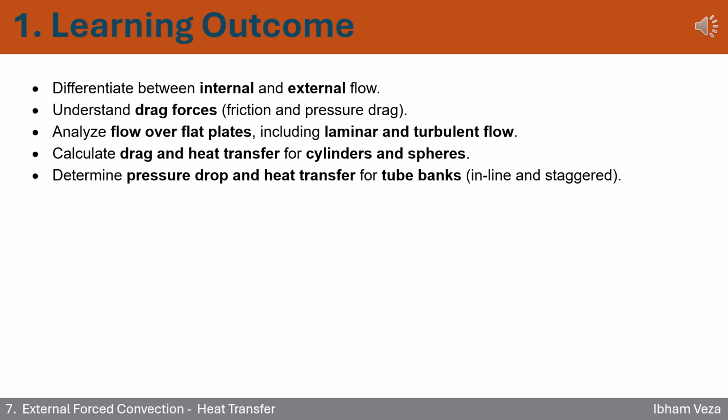There are two types: friction drag, which sticks to surfaces, and pressure drag, which comes from flow separation. Understanding these helps you figure out how much energy is lost in moving fluids. Then, you'll get hands-on with flow over flat plates, especially learning how laminar flow, the smooth kind, transforms into turbulent flow, the chaotic kind, and what that means for heat transfer.